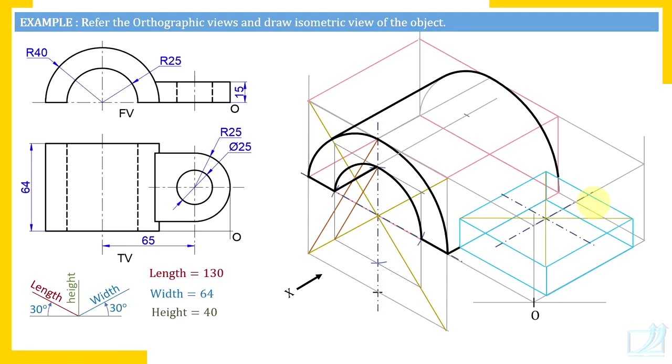Now in which 2 quadrants you are not drawing the entire circle here. This outer edge is a semicircular edge. So one shorter arc and one longer arc. The center of the longer arc is in the diagonally opposite quadrant, and where is it? At the end of the shorter diagonal. So this point is the center of the longer arc. And you want to draw the smaller arc in this quadrant, so its center is in the same quadrant.